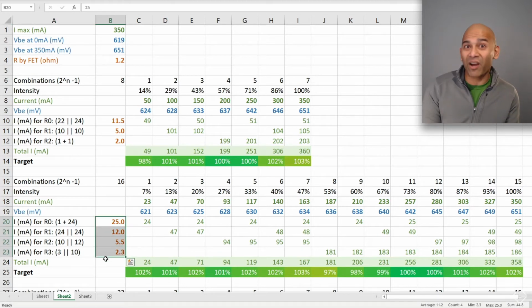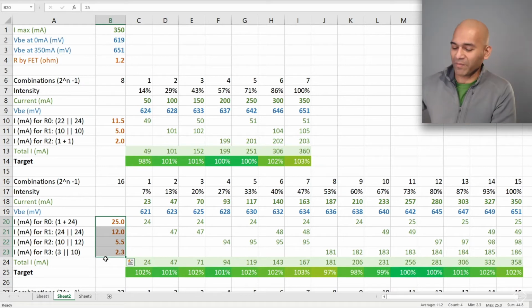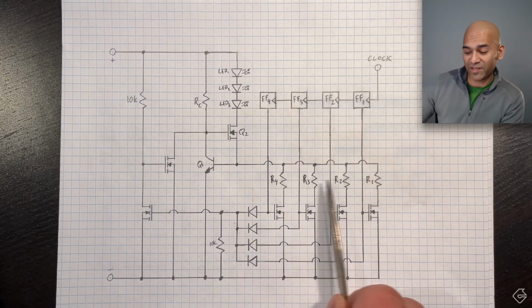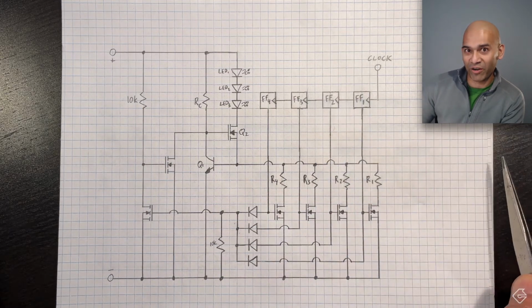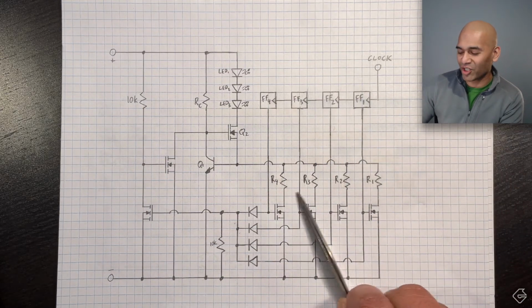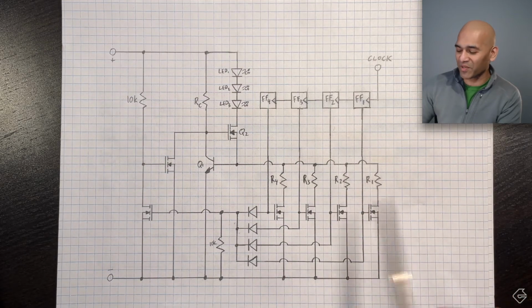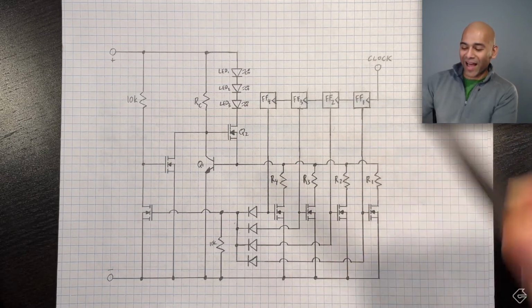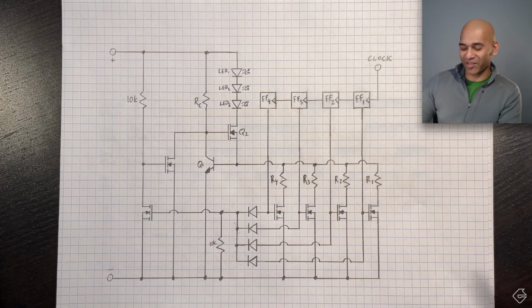These 4 numbers are the resistor values that I have to put into our circuit. So, bring back the schematic: these 4 resistors in our current hardware are not these numbers, and I need to change these 4 resistors to those numbers. So I'm going to do that while I adjust all of our circuitry.